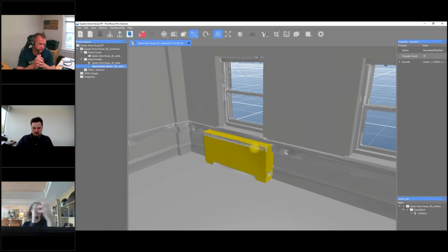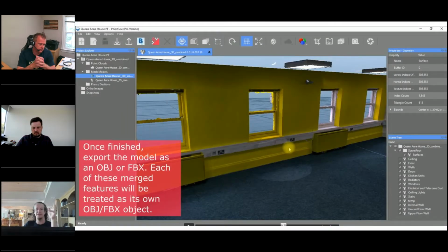And you can go through and grab these surfaces and say, oh gosh, these surfaces are an object. Those are heaters, and this thing is a wall, which is a lot easier than manually trying to window all the points and break them out thing by thing, right? You're able to pick surfaces and quickly go through and do this added intelligence work with segmented meshes. It's a fun, interesting way to process the data.